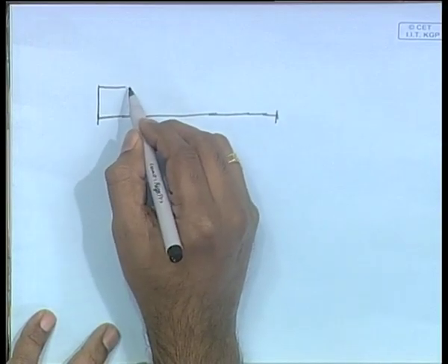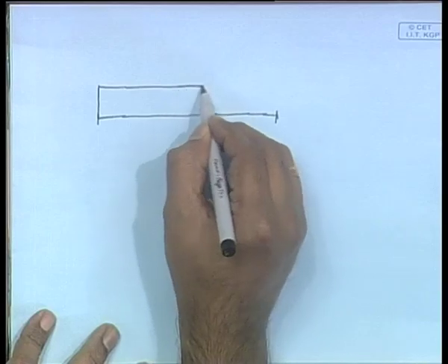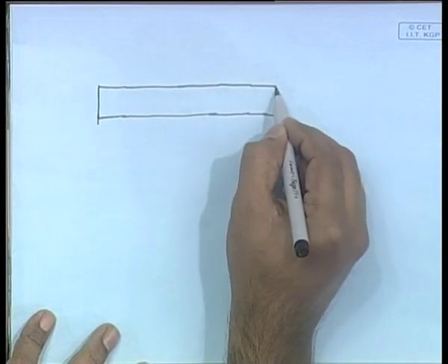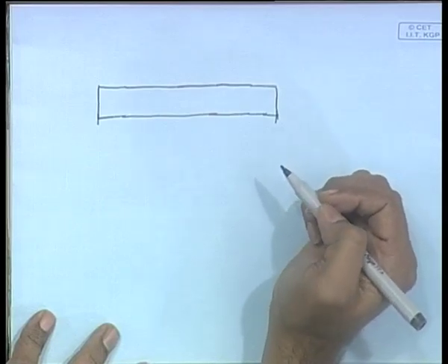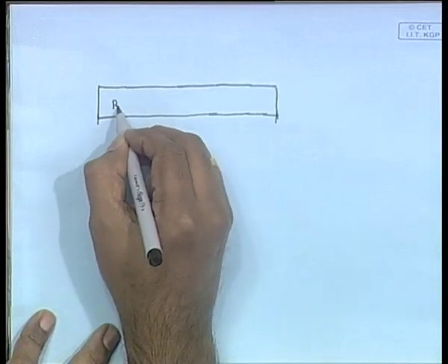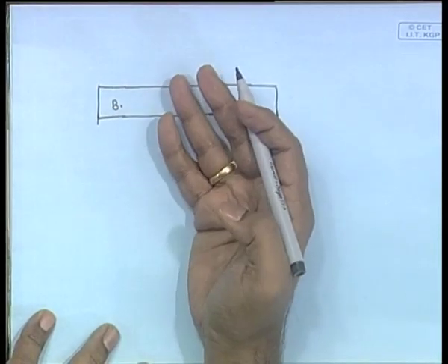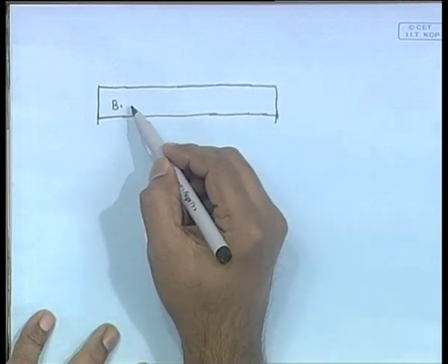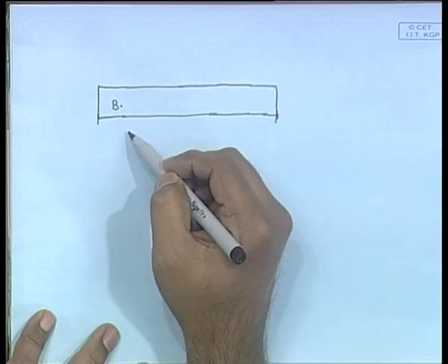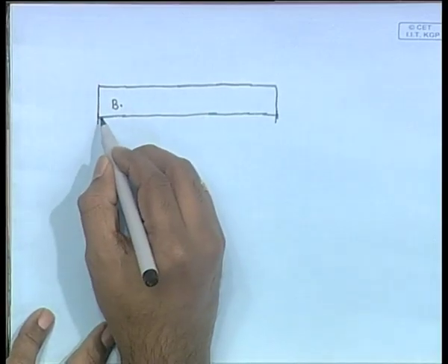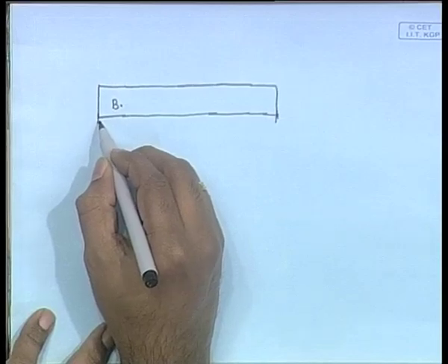For a box shaped barge, when it is floating, you will have a buoyancy curve like this. This will give you the buoyancy curve. You can draw it either way, some books usually write the weight of the ship on the top and the buoyancy as negative. Here they have drawn it this way. So, buoyancy is at the top and then the weight curve is drawn below.